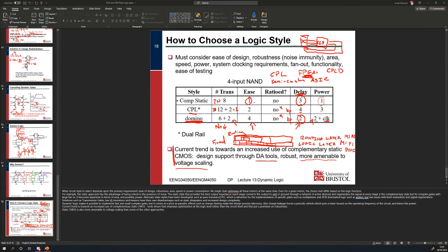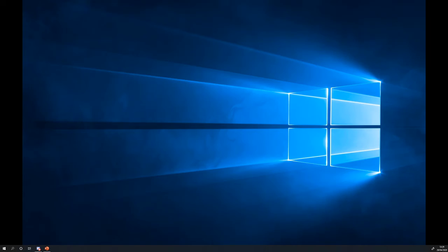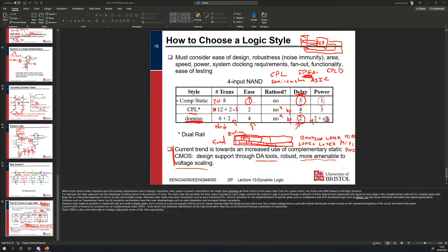I'm not sure what those are. They're all NMOS transistors. Okay, so we've got a VDD with the inputs of the NMOSes connected up to it. So they're acting as pull-up transistors, weak pull-up transistors, I presume.